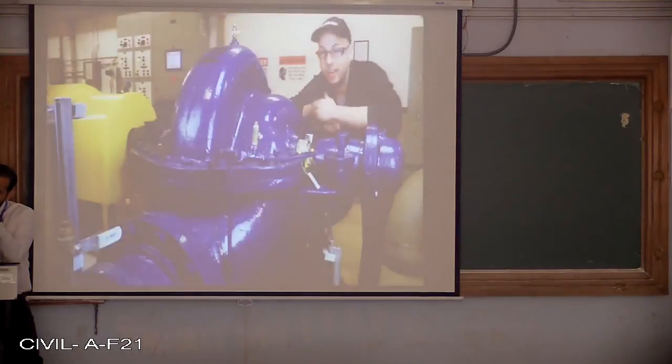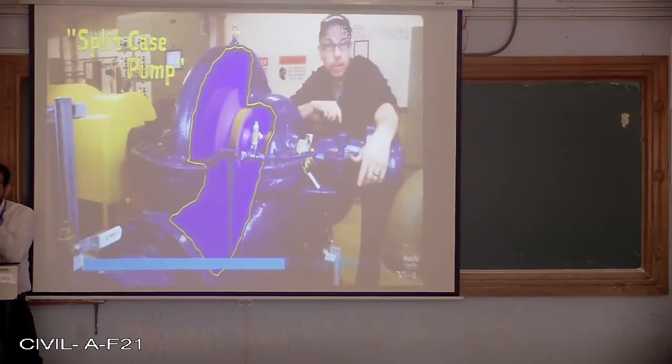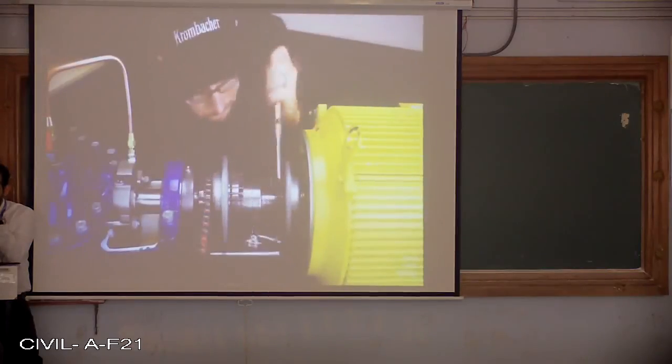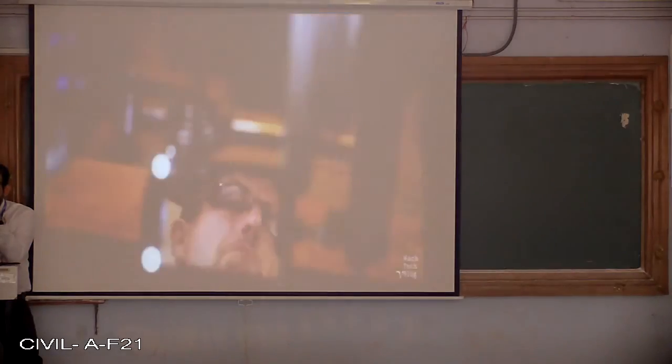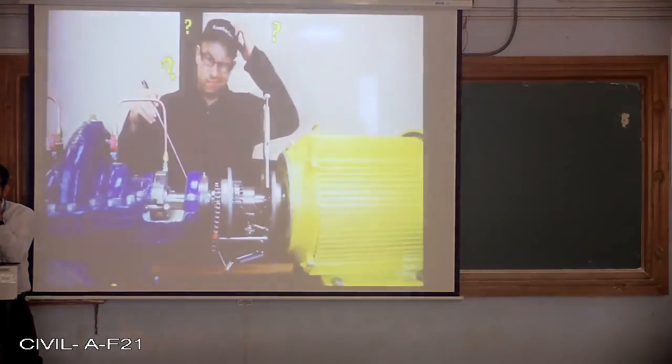A more effective solution is presented if the impeller is supported by bearings on both sides, called a between bearings configuration. There are many manufacturing sizes and styles, but one characteristic common to all of them is that they require proper alignment of the shafts, and that can be a very finicky process indeed.